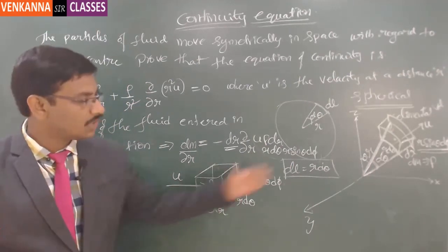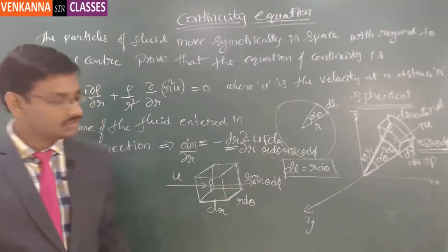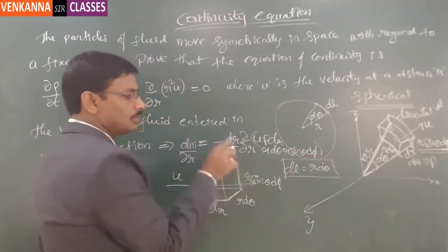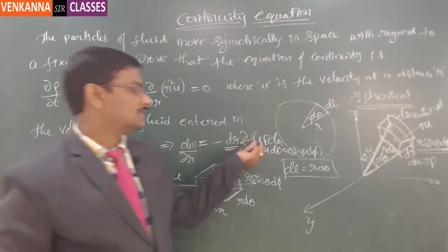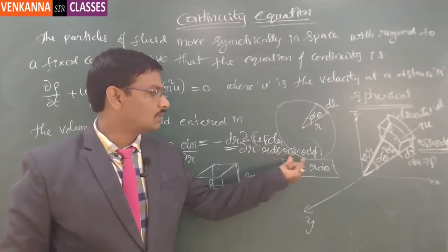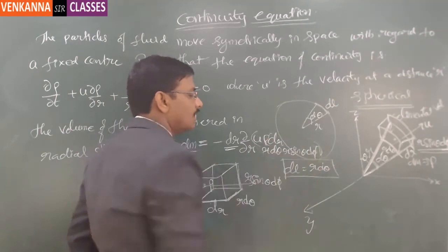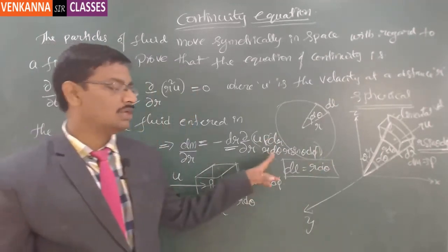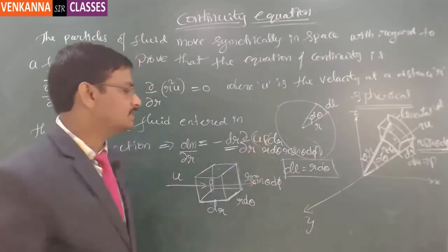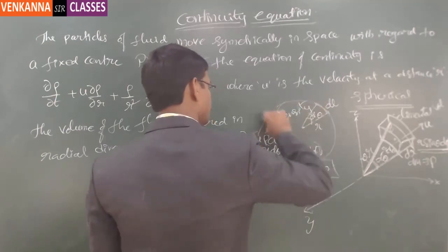So this is exactly what we have done, except for the shape. So this is dou by dou r of the mass of the fluid within. The mass of the fluid you can get because there is a velocity u, into rho, into dr, into r d theta, into r sin theta d phi. So dr, r d theta, r sin theta d phi is nothing but the volume part, and this is rho, the density, and u is the velocity.